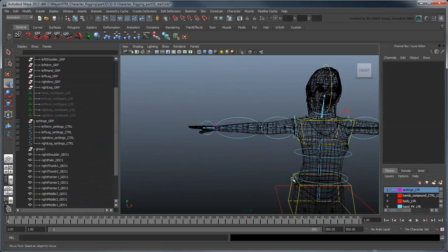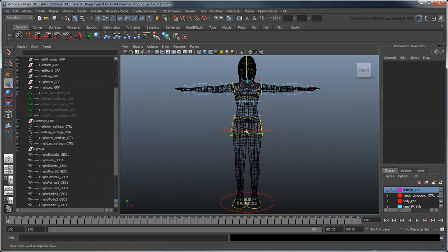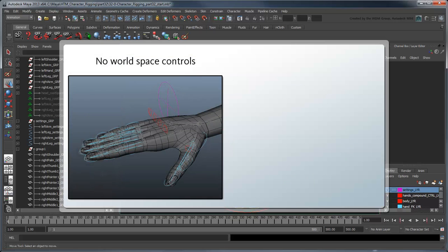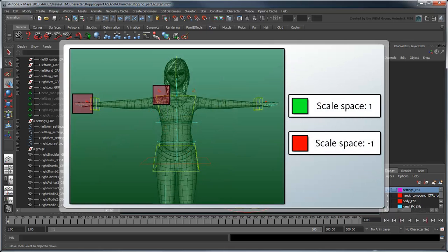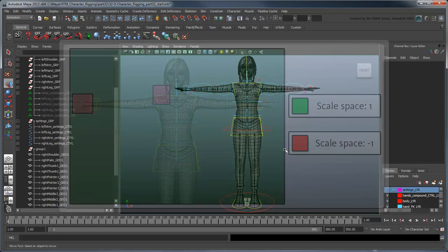Finally, the hand and shoulder present an interesting case. Because of the nature of the hand manipulation, and because the shoulder's translation-based controls actually do require an inverse relationship to its left counterpart, we can use a mirror-duplicated version of both these body parts. Being able to make a decision like this is one of the advantages of building a rig piece by piece instead of as one skeleton.